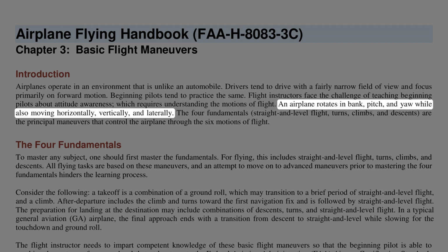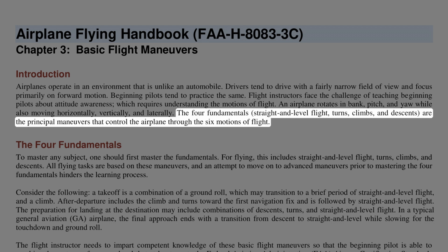An airplane rotates in bank, pitch, and yaw, while also moving horizontally, vertically, and laterally. The four fundamentals, straight and level flight, turns, climbs, and descents, are the principal maneuvers that control the airplane through the 6 motions of flight.